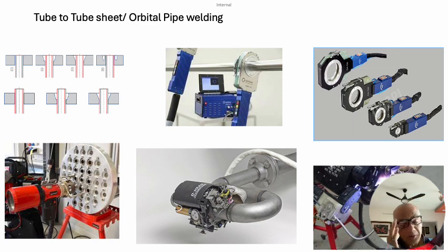So when you are going to melt at the edge, only on the top of it, and some of the joints require even the tube welding at the other end. So when you are welding onto the other end of the tube sheet, which is the tube going straight through the tube hole and getting attached to the other side of the tube sheet, it becomes impossible for manual welding, because you cannot see. The diameters of the tubes are between 19 millimeters or even smaller, sometimes 12 millimeters also, and go to a maximum of 2 inches, that is 50 or 55 millimeters.